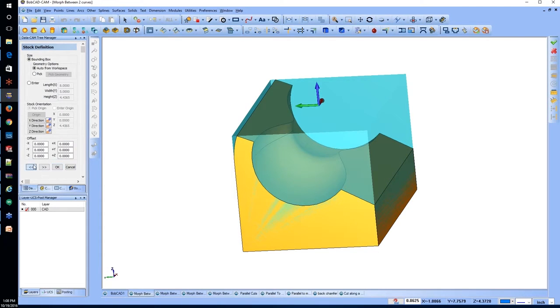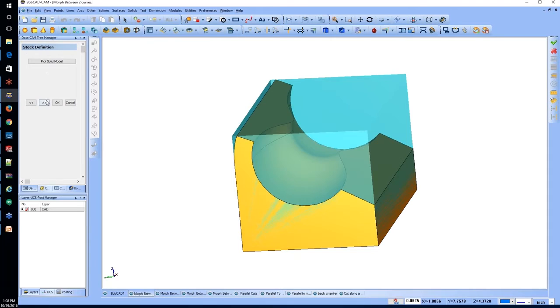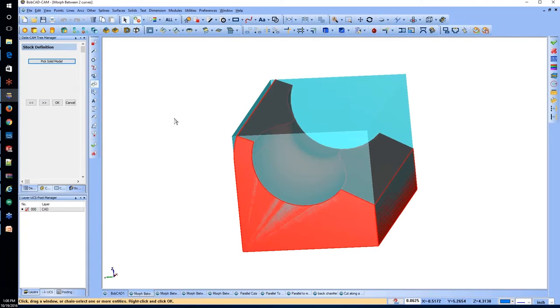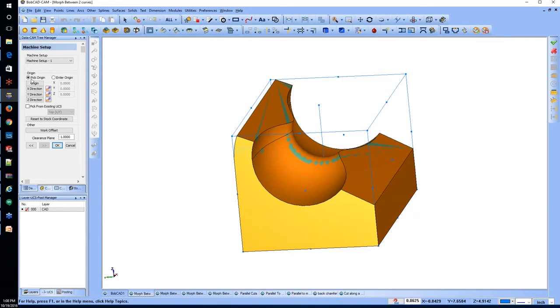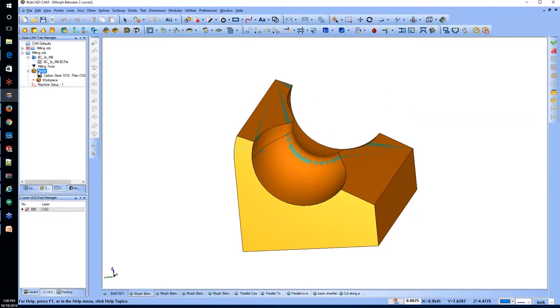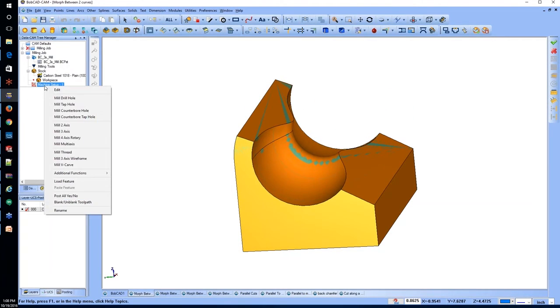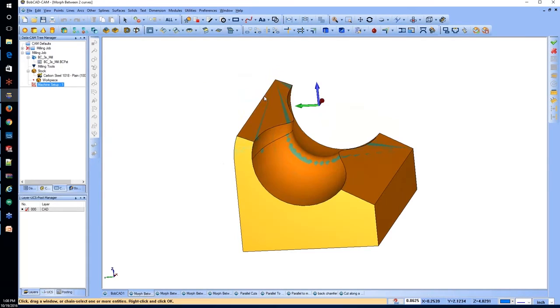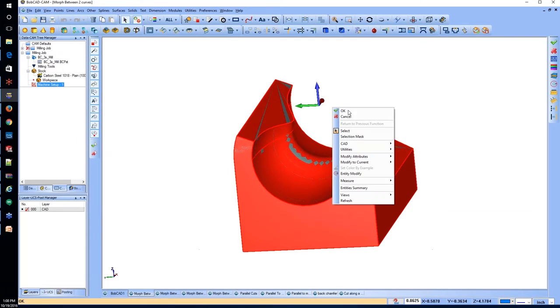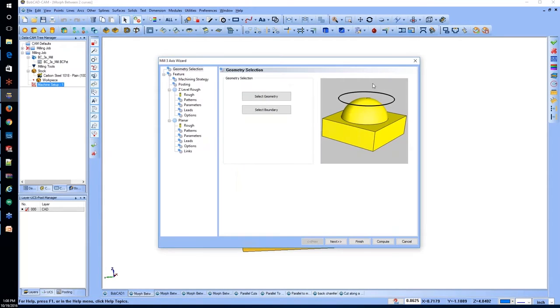What we're going to do is solid model stock for this one. Pick the solid model. Now, once you have that set, we're going to right-click on Machine Setup. What we'll do first is start off with a 3-axis toolpath. Not saying these toolpaths aren't great, this is just a tough surface to get a proper toolpath.